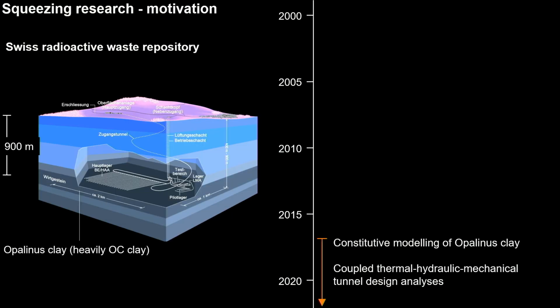And finally, for 6 years, we have investigated the behavior of the so-called Opalinus clay. Opalinus clay will be the host rock for the Swiss radioactive waste repositories. And that demands constitutive modeling of the Opalinus clay, also coupled thermal, hydraulic, mechanical tunnel design analysis.